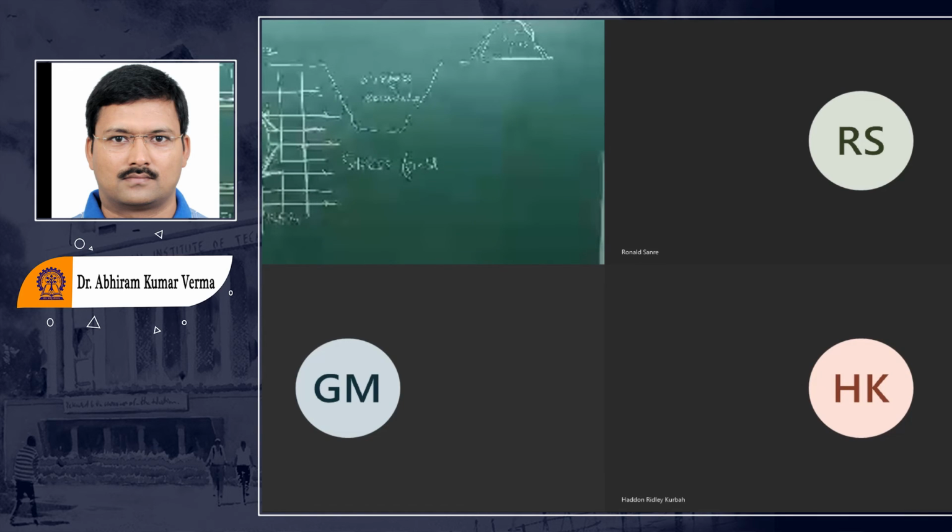So what will happen? The in situ stress which was there at this point, equal to sigma v, your gamma h, has changed because additional stresses have been added to this point because of the stress shifting from nearby areas. This is what happens to any underground opening.